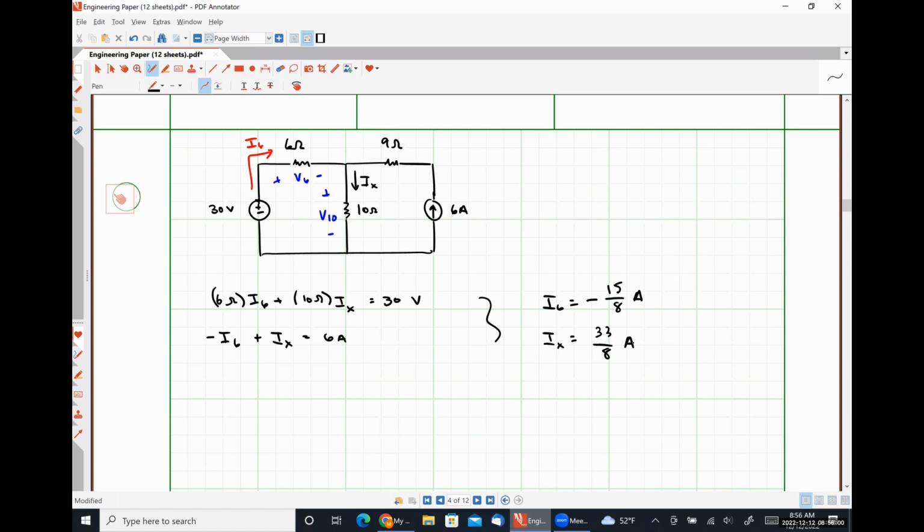I'm done here. I want to show you guys your in-class assignment for a moment to explain exactly what I'm talking about there, but I do want to make a point to you guys that we did not cover an example like this in class today, but you will see at least one on your homework that contains a dependent source, okay? So everything that we've dealt with here today dealt with turning off independent sources, okay? So if you ever have a dependent source in your circuit, you can never turn it off. Dependent sources are always on. Independent sources are the ones that you turn off in your analysis when applying superposition, okay?